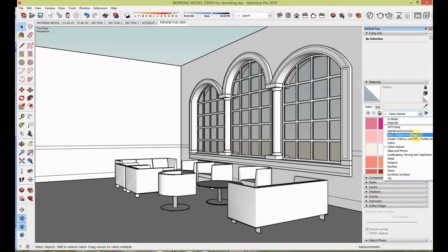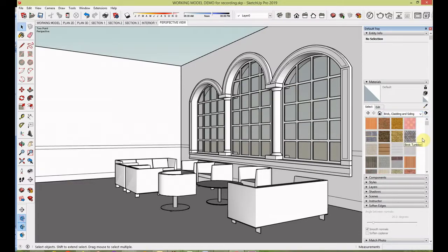One of the things you should remember is that when you are converting a SketchUp file to Photoshop, you're going to lose a little bit of the vibrancy that putting the material in directly in Photoshop would give you. And there's ways around that, and we can create some adjustment layers in Photoshop, and we'll talk about that when we go to Photoshop, but it's just something to keep in mind.